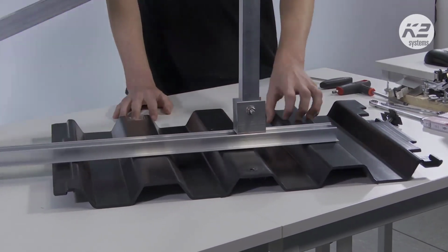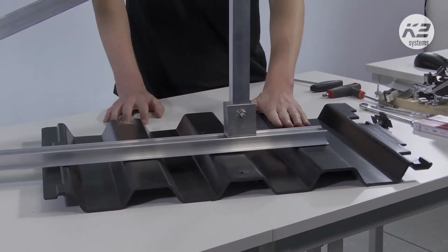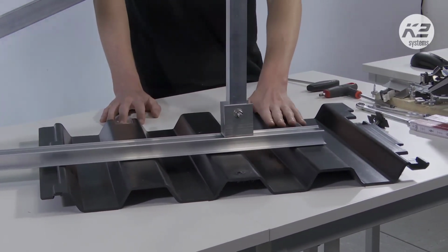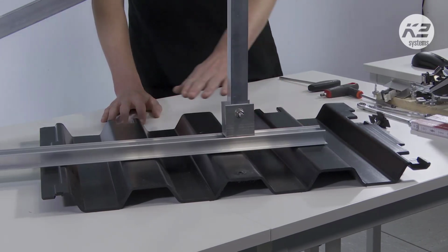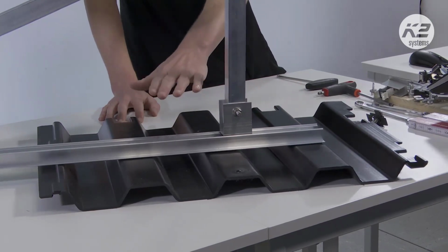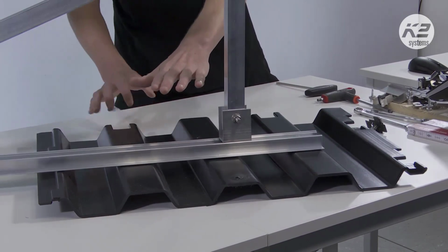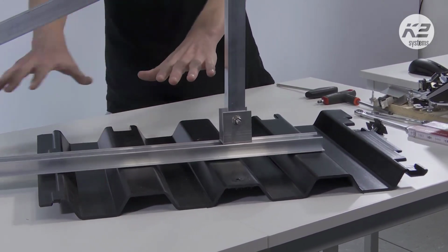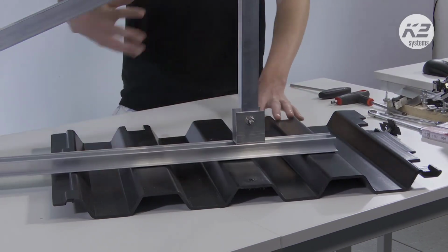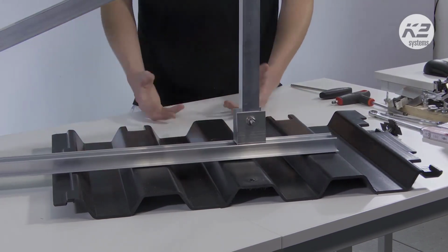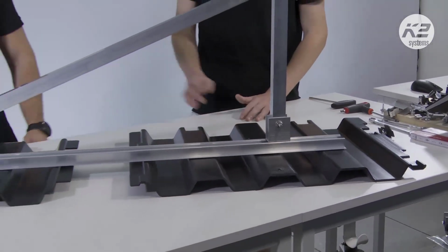But using these PE plates, we are able to utilize the weight that is already on the roof. So if you have a green roof or a gravel roof, you will have maybe 8 centimeters of gravel sitting on here. If we know that gravel density, we can use the weight of all of the material above it to hold down the system. So you may not need so much more ballast as what you think you would need by raising it up so much.